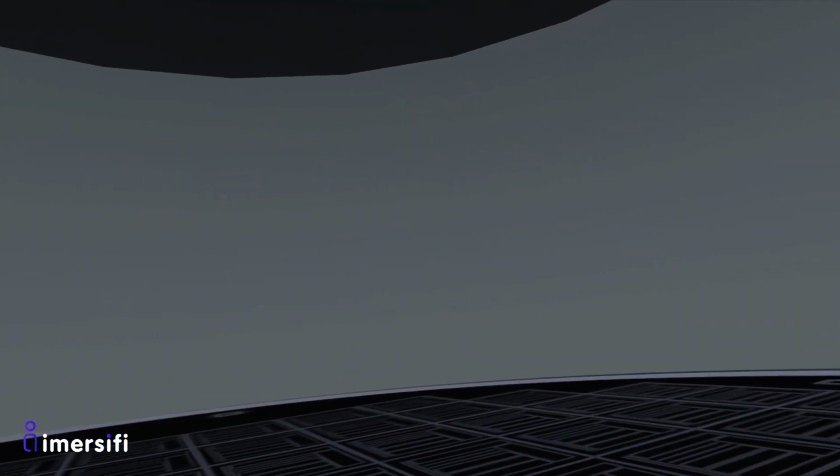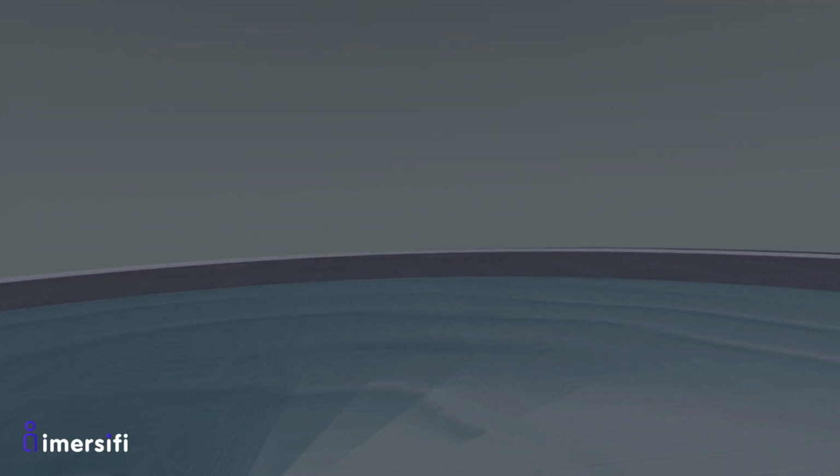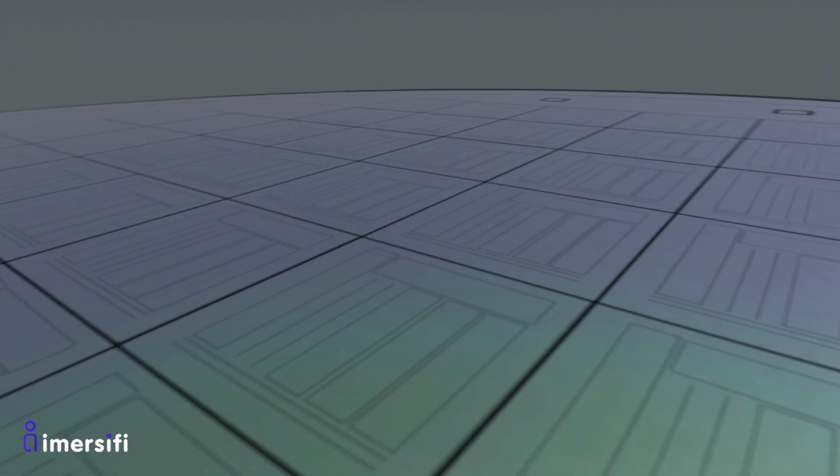Now we are on top of the wafer and under the mask. Let's turn on the UV light. The photoresist on the wafer changes its physical properties when exposed to UV light. We can dissolve some of the photoresist by using a developer solution, leaving the desired pattern on the wafer. Now let's move on to etching.